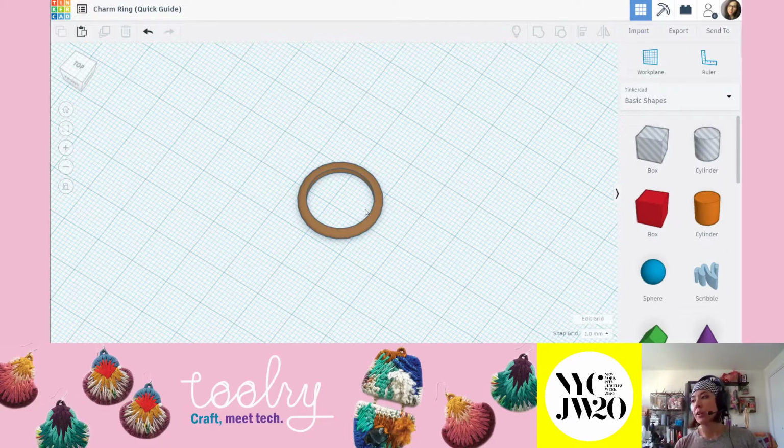In a more traditional method of fabricating this ring, you would build your ring shank, then purchase your jump rings, and then solder them on and attach them. We don't have to worry about that. In this case, we can just assemble this, upload the assembled file into Shapeways, and then they will fabricate it. However, you have to make sure that you have 1 millimeter of clearance all around every object that interlocks. I just wanted to give you that disclaimer so that you can understand why we're doing the next steps the way that we do them.